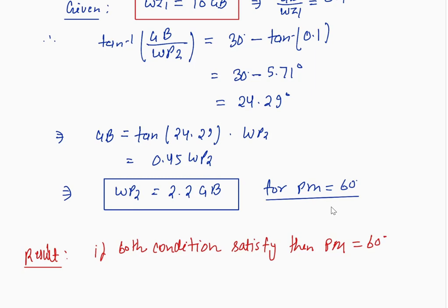We will use this concept in the design of a two-stage op-amp, because there we also want 60 degrees of phase margin. So we want to know where we should put our second pole so that we get a phase margin of 60 degrees.